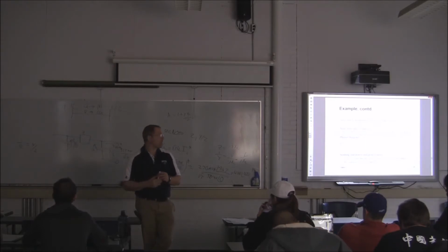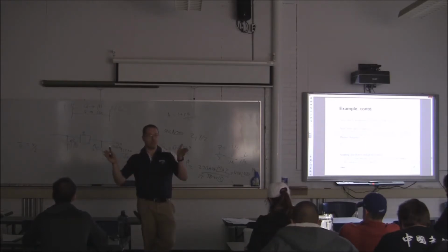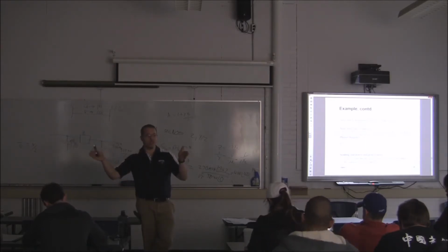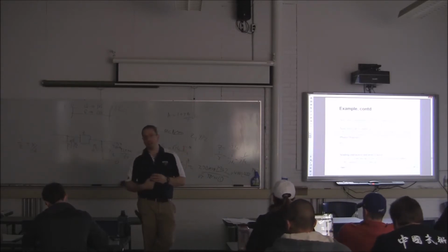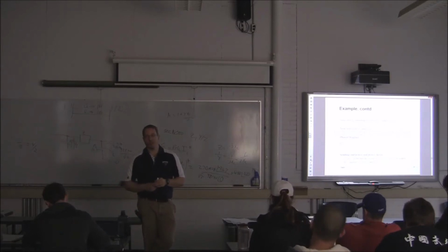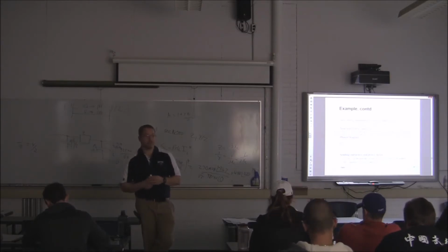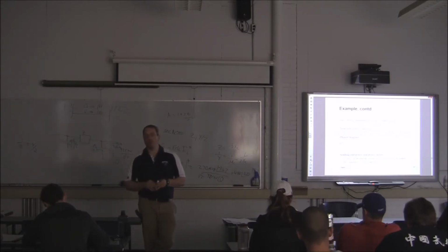And so that's what a lot of people will do. They'll just say, hey, what's the voltage at this end? It's too low or too high. That means there's too much reactive power flowing in that direction. So they'll try to switch in some cap banks. That will boost the voltage up on one end, which means you don't have as much reactive power going in that direction.